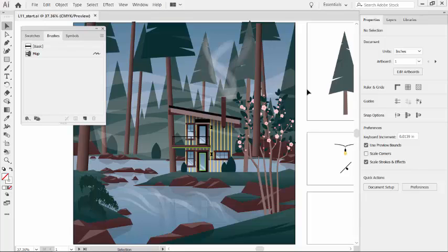We'll work with pattern brushes. And pattern brushes are made up of separate sections or tiles. And when you apply a pattern brush to artwork, different tiles of the pattern are applied to different sections of the path, depending on where the section falls in the path.